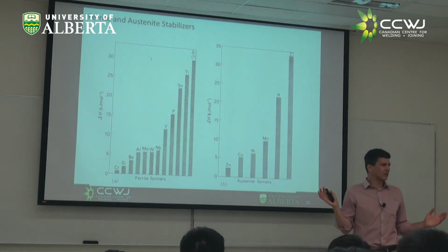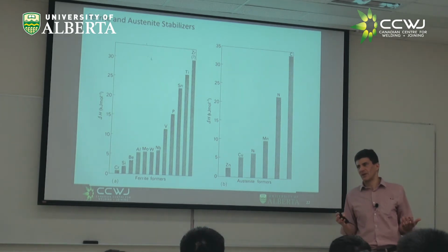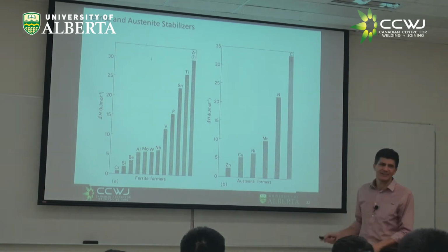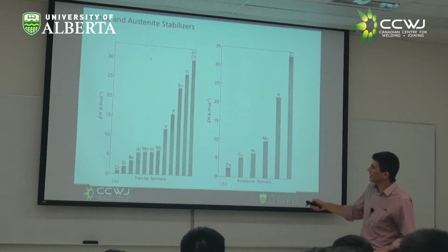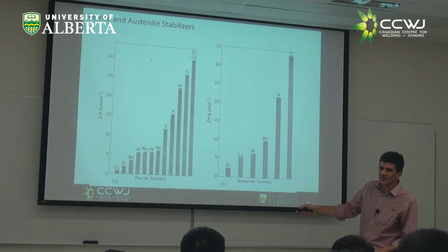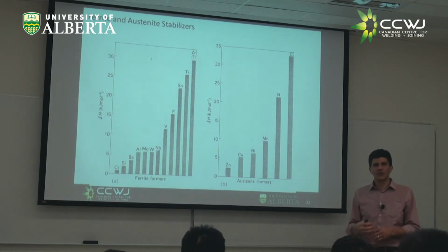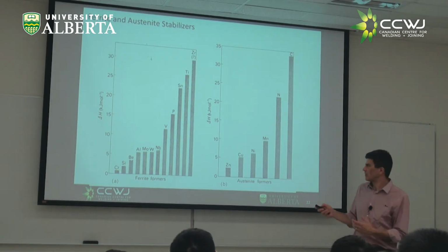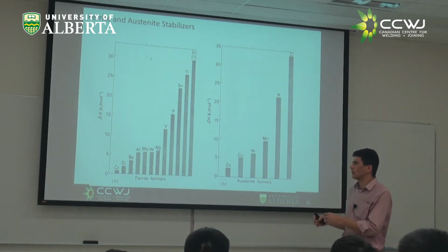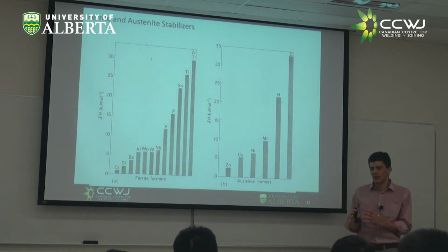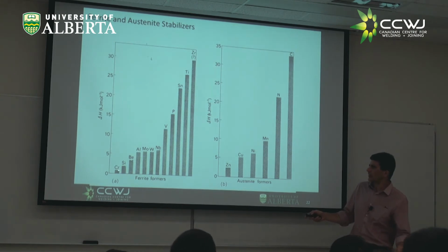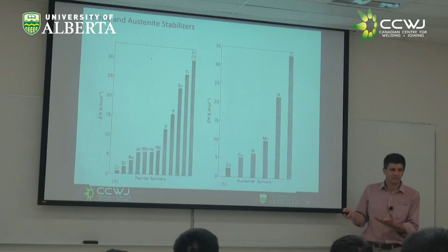Austenitic stainless steels, as you can imagine, want to be in austenite. And what do they have? Lots of nickel, right? But if you don't put too much nickel, you see chromium here, which makes it stainless, is a promoter of the ferrite. So right there you start to see how some chemical elements like chromium, which is there to make the steel stainless, need to be counterbalanced with lots of nickel to be austenitic.